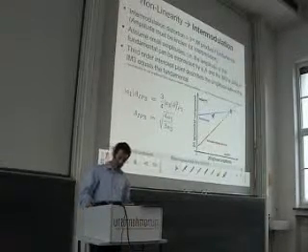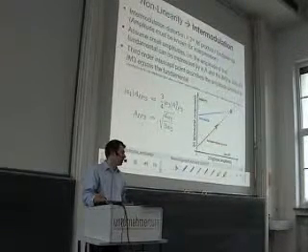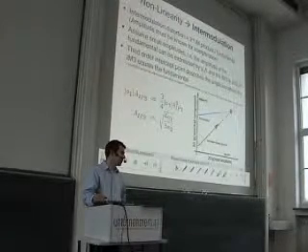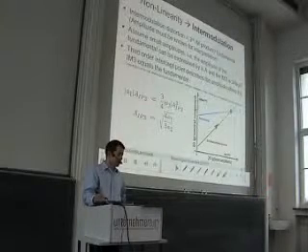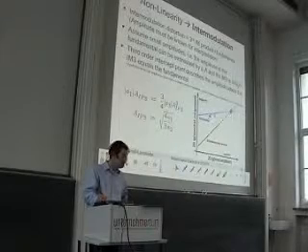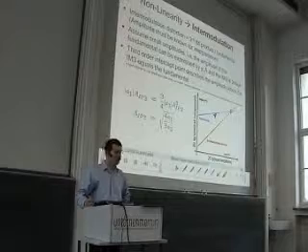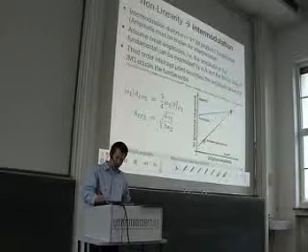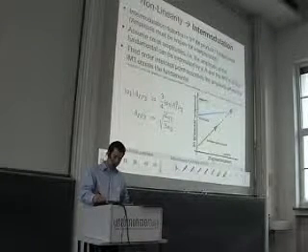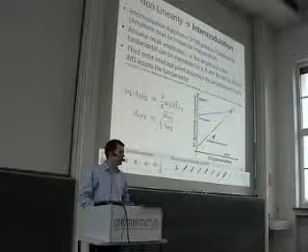Good. By the way, these are typical curves you see for ADC measurements. You often also make such a plot for the harmonics. Then you usually have your fundamental that scales with A, and then your harmonics are coming up with a much higher power of the amplitude. The third harmonic with A to the power of 3. The fifth harmonic usually starts much lower but comes up with A to the power of 5 and so on.